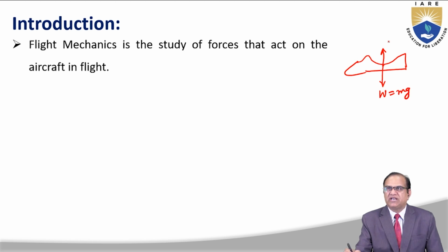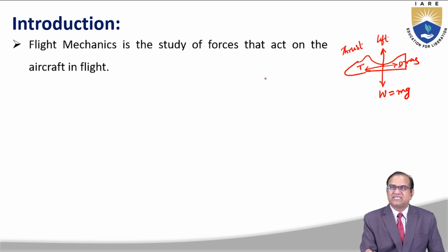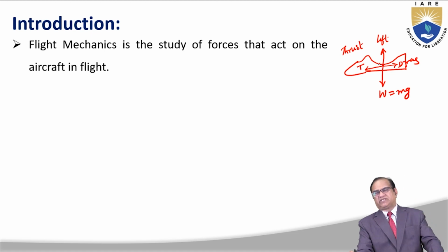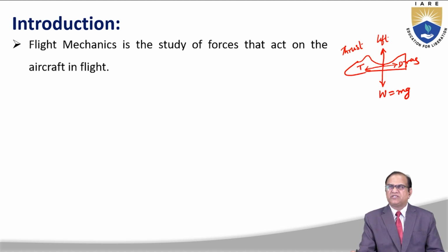To counter this weight, we need the lift. Then if it is moving, there will be a drag. To counter this drag, we should have the thrust, which is called T. So flight mechanics is the study of forces that act on the aircraft in flight. In different systems, their parameters, numbers, and quantities may be different, but these four forces will be acting on any aircraft.